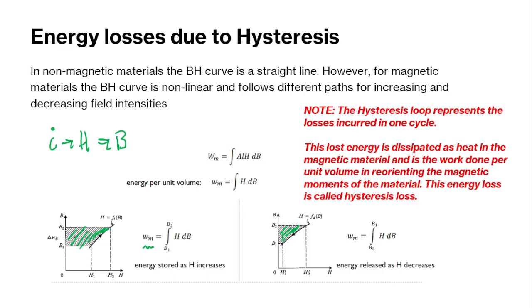That makes sense. But where is that energy going? Where the energy is going is the environment, basically. But it has two types of losses. You have I squared R losses and you have hysteresis losses. And the hysteresis losses include eddy currents. The eddy currents are that type of loss. So you have eddy current losses and you basically have I squared R losses, right?